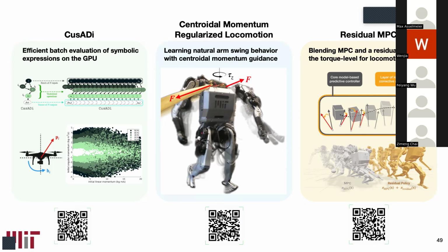That's a good question. The question was basically, have you considered behavior cloning, DAgger, these kinds of approaches to copy the MPC solutions? I did not do that direct comparison because in my opinion, MPC is not a perfect prior. We don't want MPC to be the thing we copy from because it's based on a lot of assumptions that aren't true. For example, in the MPC trajectory video I showed of it walking with the predictions going forward, the desired path for that MPC controller is literally just the current position copy-pasted along the horizon. We don't have a good sense of how to design an MPC controller prior that's correct.